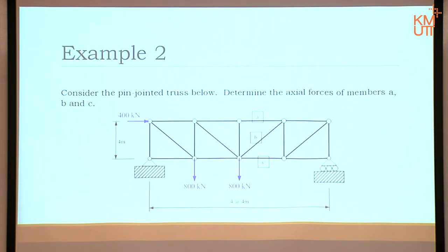There's another truss, a bit bigger. The question doesn't ask for all the member forces. The question asks for only member A, member B, and member C. And it only gives three names. Usually this kind of truss, when you need to know only certain members, not all. Or sometimes even though you need all, you can do the section method. This one here, section method will be quicker. I will compare later. Okay? Well, first things first, we have to agree first. Oh, we need reactions anyway.